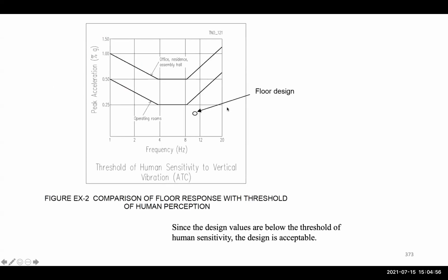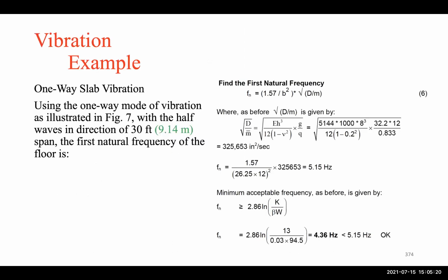Okay, so as you can see here, that's what we checked here. So you can go through that, but here to show that what we checked is less than what we have. So this is okay for vibration. If it comes above these, then we have to do something: increase the mass, increase the stiffness, or increase the damping mechanism. Okay. Again, it continues here.